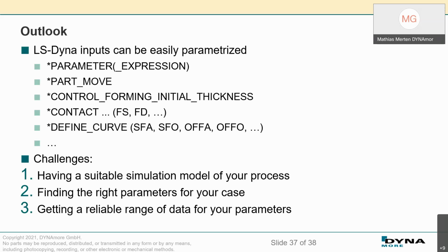So some deviation inside the plane perpendicular to the working direction. Or you could iterate the initial thickness distribution of your blank. Usually we assume we have a constant thickness of, in this case, 0.7 millimeters. But from the hot and the cold rolling mill, we know that there is no constant thickness. So with that keyword, you can override this initial constant thickness with a vector and a thickness distribution, and this can also be addressed with parameters.